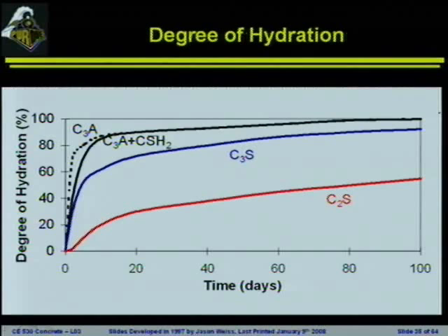All right, the other way that this could be done is using a SEM image. You could use a scanning electron microscope image, and look at how much of that cement has been used up as a function of time. This would be very similar to the cartoons I showed earlier, where we were talking about setting, with the white cement particles being inside of the blue. You could measure how much of the surface area of white is reducing over time, and that tells you how much of the white material, or the cement, has been used up as a function of time.